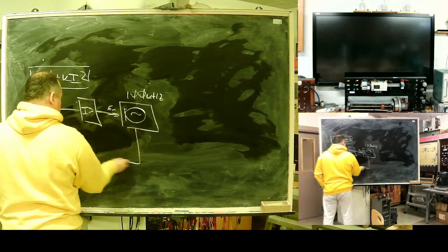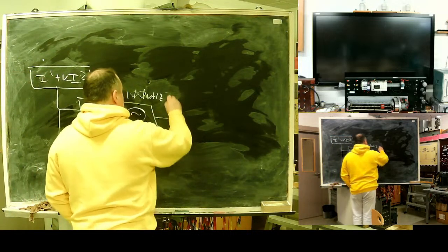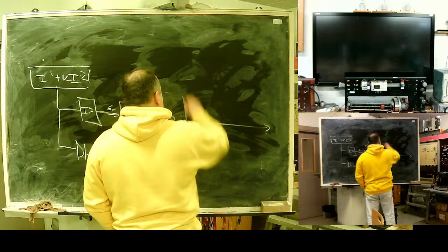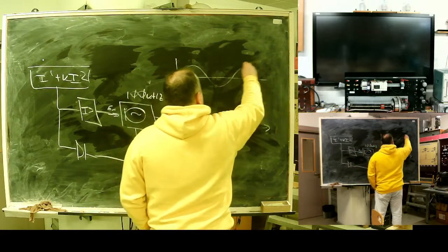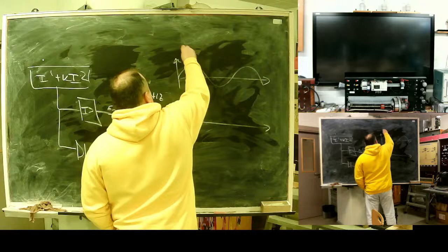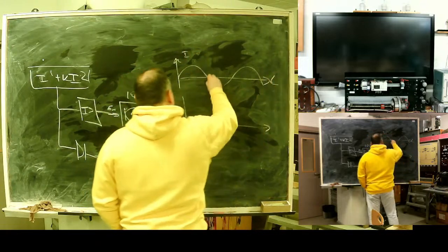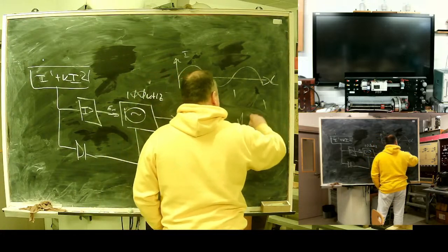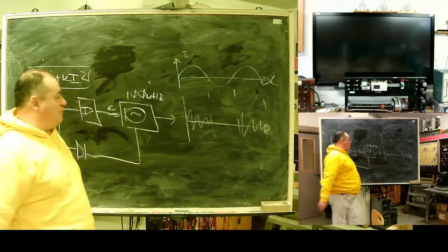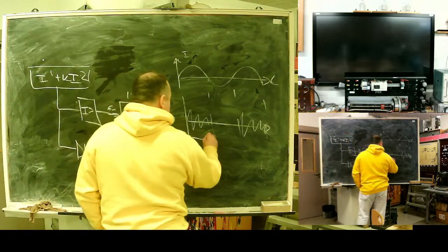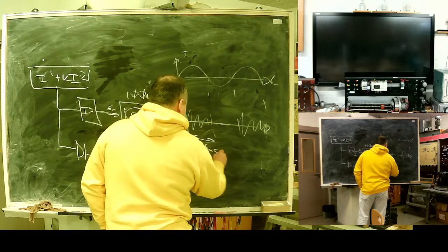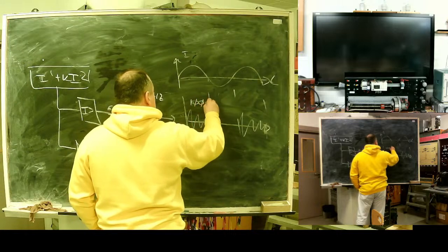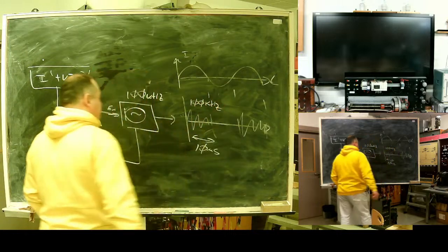This enables and this manipulates. Resulting signal, if primary current is something like this, will in a simple way be a set of high frequency bursts. Approximately 10 millisecond bursts of 100 kilohertz signal.